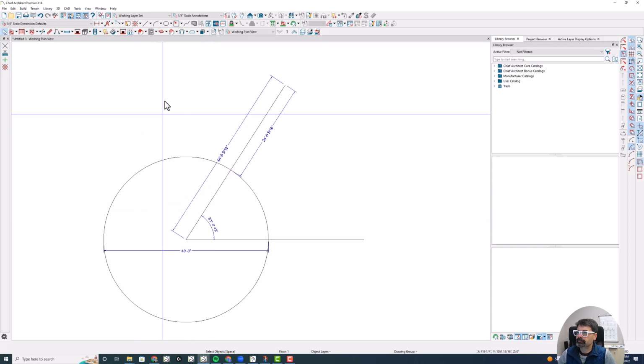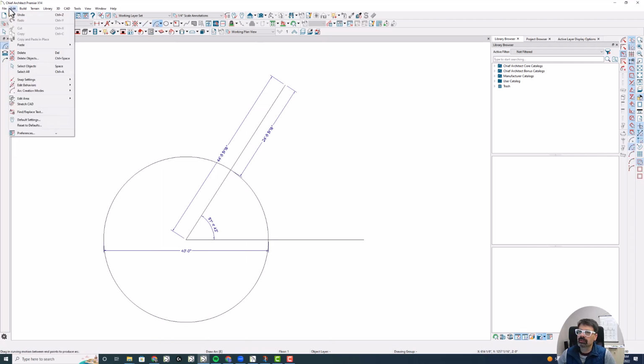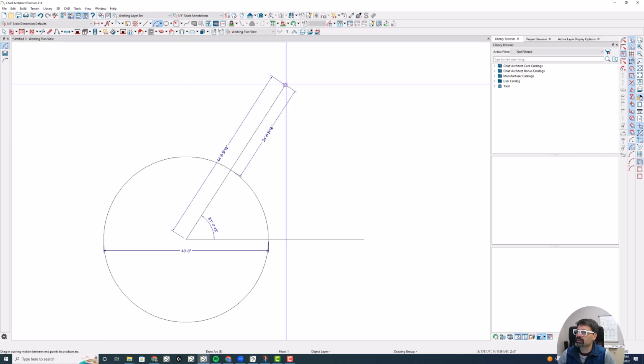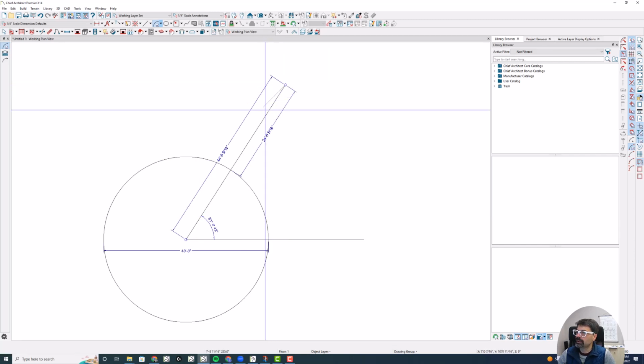multiple of 15 or 45 or specific calculable dimensions, really. And so then I'm going to go into arc, and there are arc creation modes I've got set up in my toolbar here. You can also go into edit arc creation modes. I like this center radius end, so I'm going to click on the center out here at the end of this line and drag it down here.